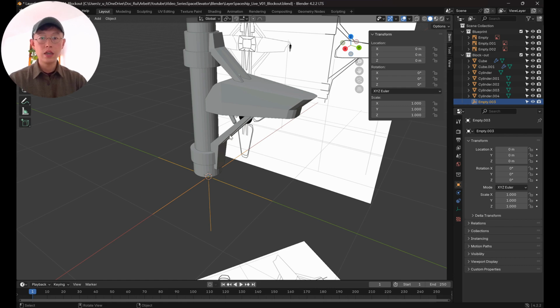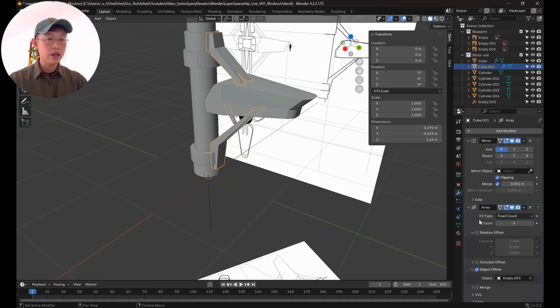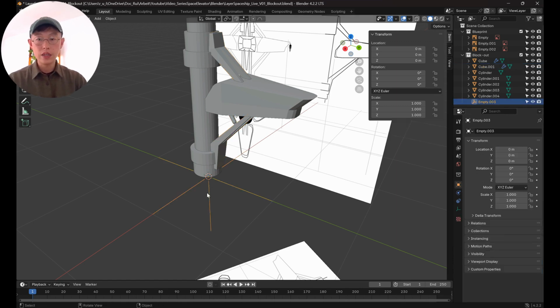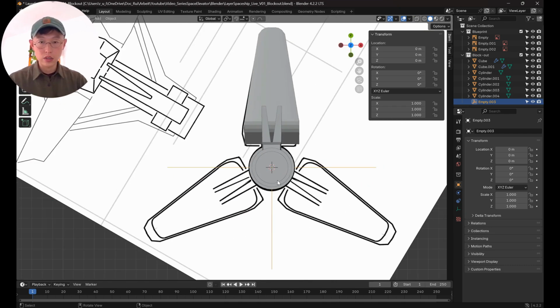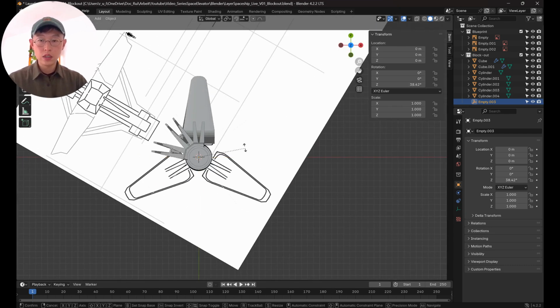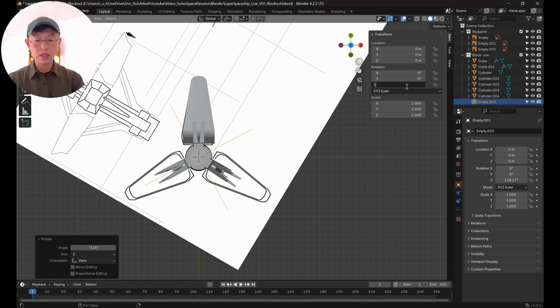And when you rotate it, you can already see that there are many of the same kind coming out of it. And I need to define how many copies I want to have. And I think the best way to do that is to look from the top view. And this would be 120 degrees.